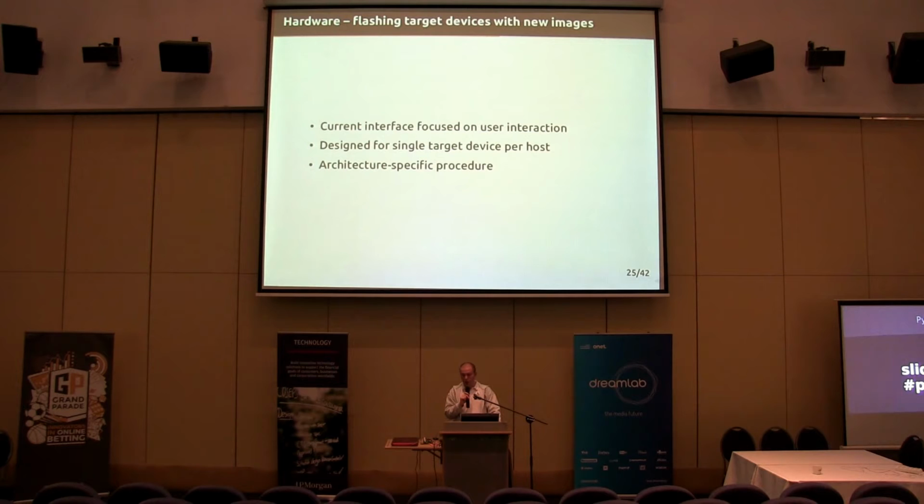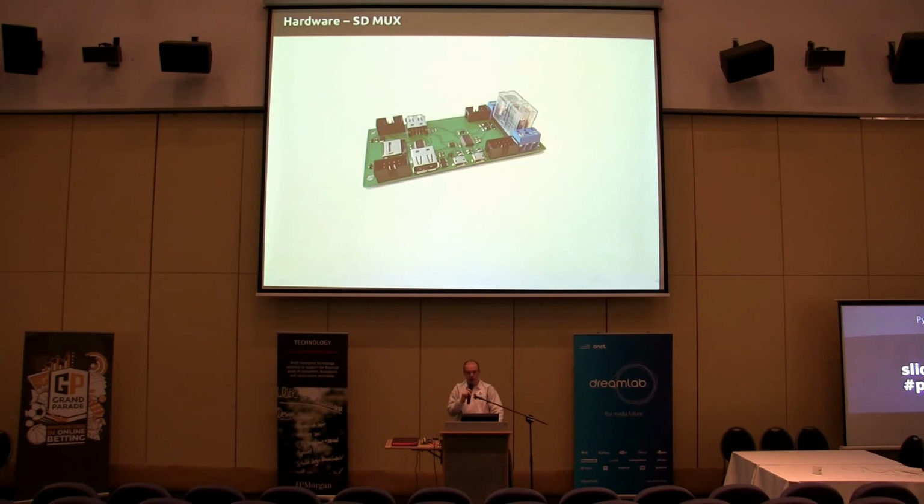However, all of the target devices share a common feature. They can be booted up from a microSD card. That's why we came up with the microSD card demultiplexer, which can share the access of the memory between a host and the device under test.